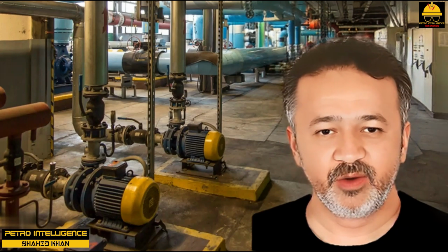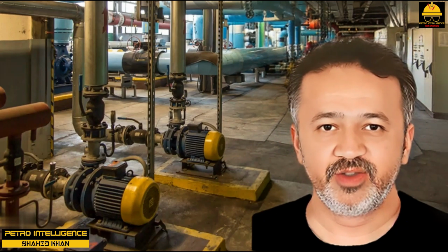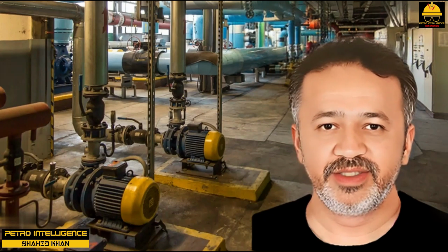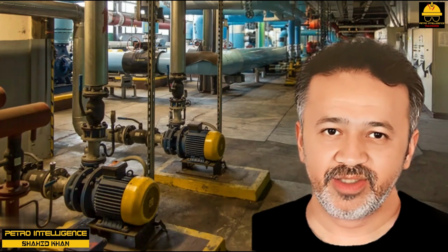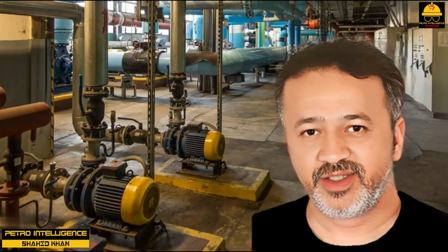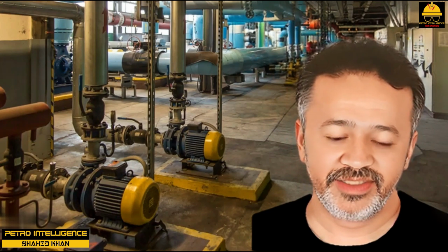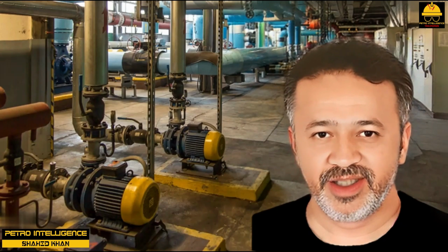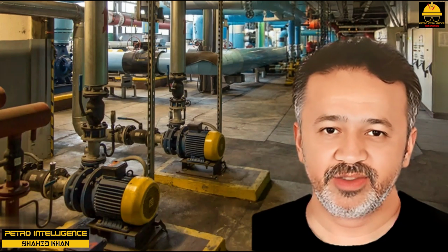At the plant, our motors are protected differently than at home. At home, our motors share a circuit with other power consumers. A circuit breaker may be rated for 20 amps, but a single motor on that circuit may be rated for 5 amps. The circuit breaker setting of 20 amps is too large to protect the motor from overheating. At the plant, each motor has its own dedicated circuit breaker, set individually to protect a particular motor from overheating, that is, the full limit amperage point.